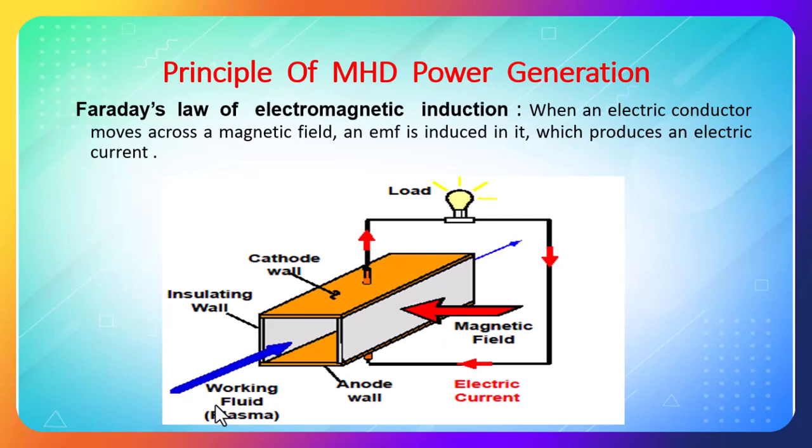Now where should I get the gas heated? It is again simple. In any other combustion, what will be the result? Heat will be generated. That heat you would normally leave to the atmosphere. Now we are saying don't leave it to the atmosphere. Bring that heated air here and pass it across this. So waste obtained from some other process is brought here, utilized, and used to generate power. That is why we call it a green energy way.